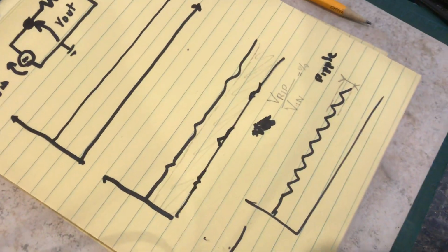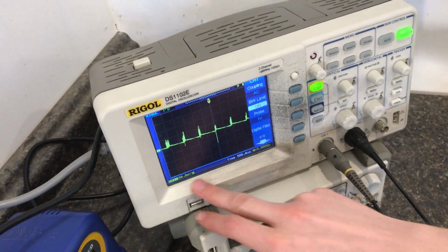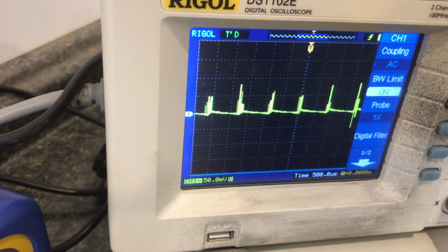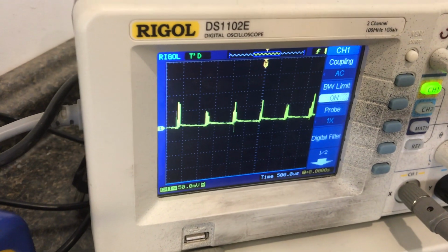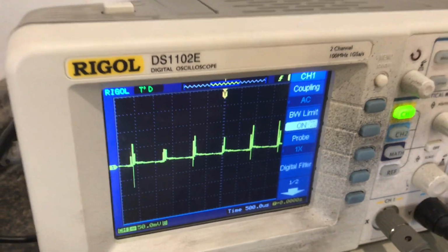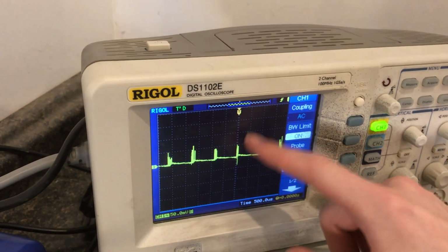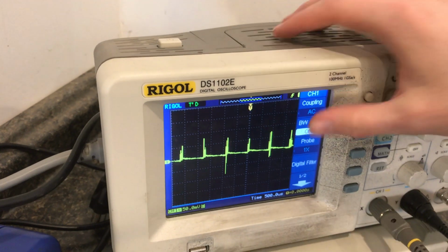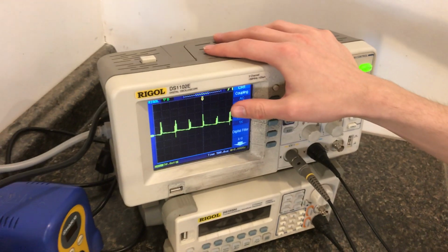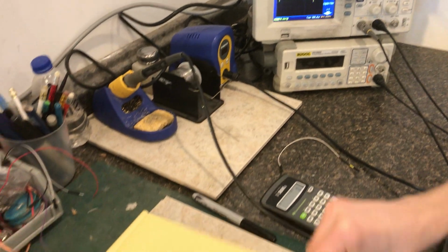And then we can scale it up on the oscilloscope, and I have it set to 50 millivolts per block. I would say, generous estimate, 80, maybe 100 millivolts. Ripple voltage, we have this kind of smaller ripple up and down, but then we have this larger, really dramatic spike, and that's what I'm going to count as the ripple voltage. And I want to write that down. Let me go to the next page.